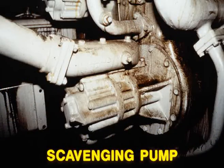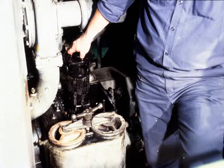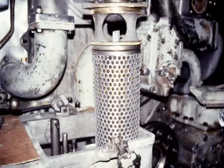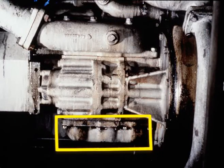We'll start by examining the operation of the scavenging system. A large gear-driven positive displacement pump, mounted on the left front corner of the engine, draws oil through a pipe located in the right side of the oil pan to the scavenging strainer located in a compartment in the suction strainer housing, which is located on the right front corner of the engine. This strainer removes large objects from the oil before filtration. From the strainer, the oil flows out the side of the housing to the inlet of the scavenging pump.